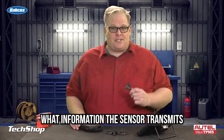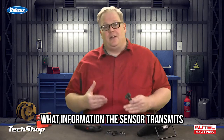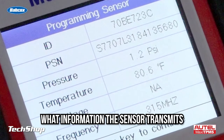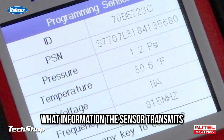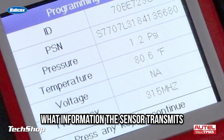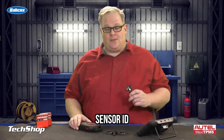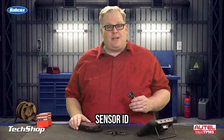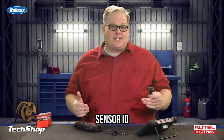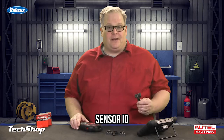So what is a TPMS sensor transmitting? It depends. Some sensors just transmit the pressure and temperature of that tire and also its sensor ID. In some cases, it'll actually transmit information on the life of the battery. It all depends on the manufacturer of the sensor and also the vehicle. The sensor ID is typically unique to that vehicle and the sensor. Basically, it's a handshake between the TPMS antenna and module and the sensor to say, hey, this TPMS sensor is on this vehicle and it belongs to me.